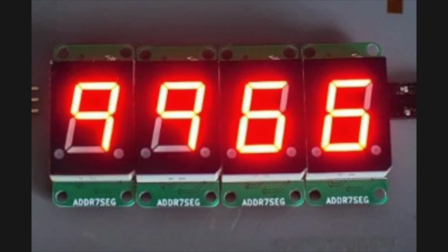So the results of the practicals will be displayed by using either one 7-segment display or a combination of multiple 7-segment displays. For example, an 8-bit number would need to be interpreted by using two 7-segment displays, and a 16-bit number can be displayed by using 4 7-segment displays, as these numbers are depicted through hexadecimal numbers.